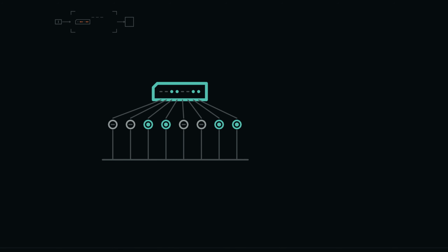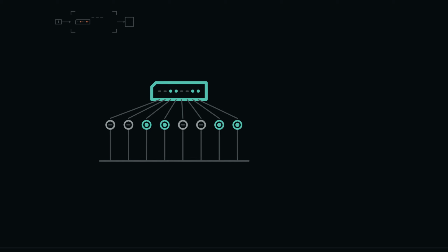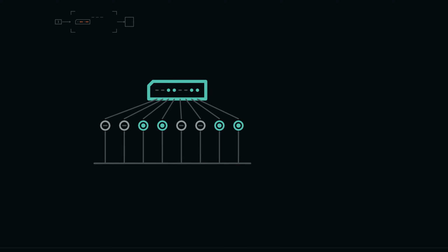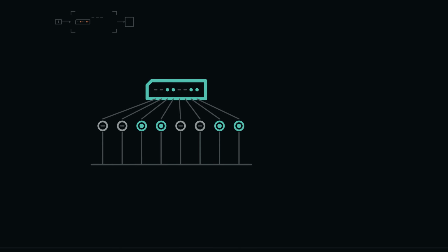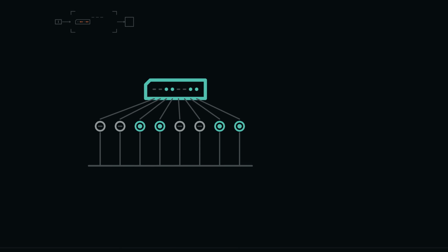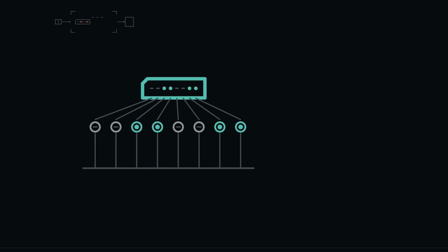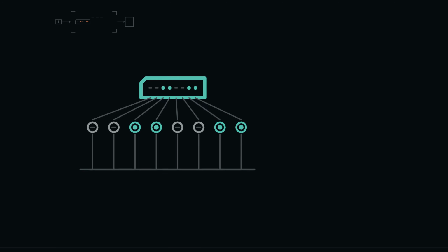Predict 2 edges. The register currently stores 00110011. A different input pattern waits outside. At edge 1, load is 0, so each selector returns the stored candidate and the register remains unchanged. At edge 2, load becomes 1 after the input has settled, so the new pattern is captured.